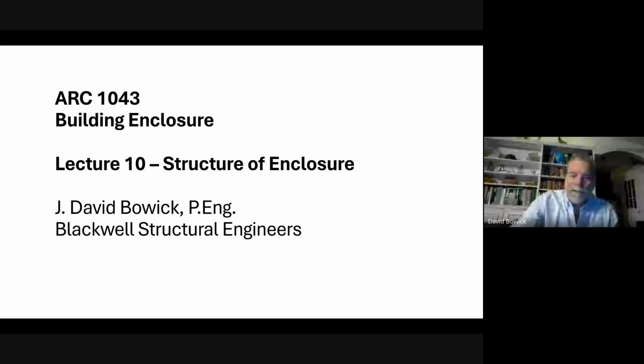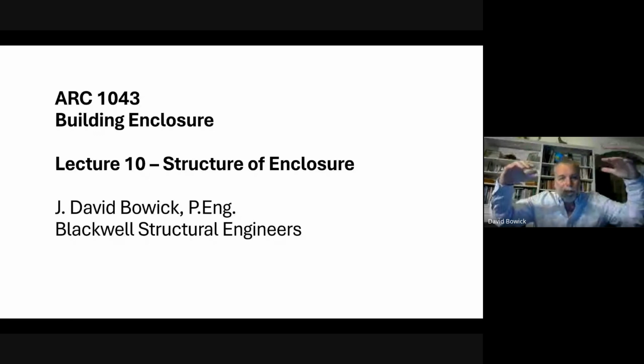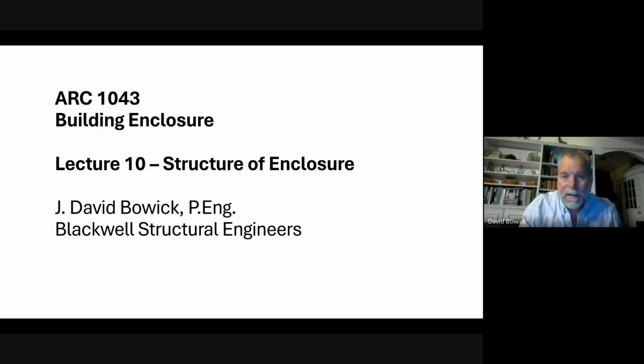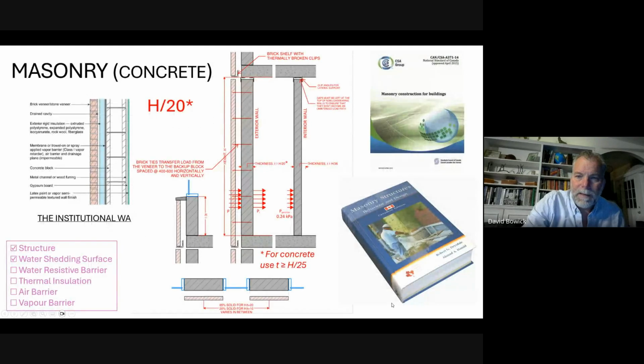That's not to say that it has to be load bearing in the sense that it has to carry the weight of the roof or the floors above. It doesn't. But all structure is subject to some amount of loads. It's got its own self weight. It's got wind applied to it. It's got interior pressures. Even interior walls have wind load on them. So that's what we're going to talk about today.